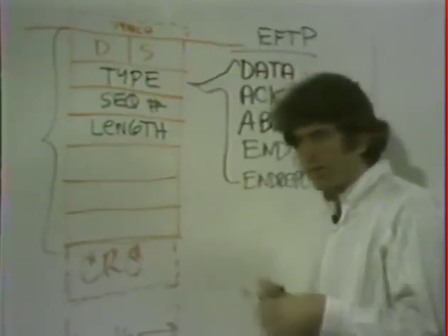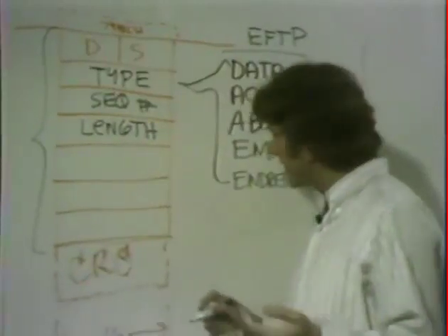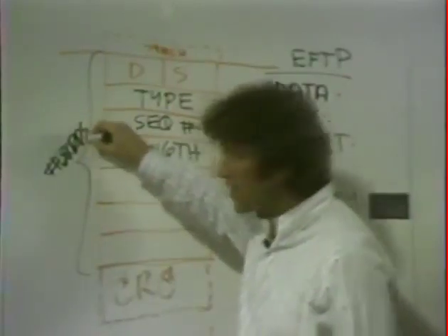And then as the packet's being received, the bits as they arrive are put into words and dropped into main memory, and then when the packet is handed over to the software, it's given a count of the number of words that were delivered. By putting a length field inside of this packet, what we do now is we have a confirmation.